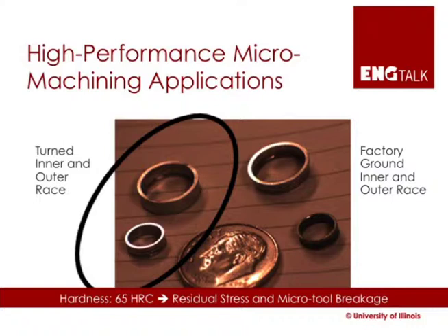And when you're machining such hard materials using microscale tooling, there are two things that you have to really take into consideration. One is, of course, the breaking of our tools. Again, these tools could be finer than the diameter of your hair. And the second thing is when you're cutting such hard materials, there's extreme heat and high cutting forces that are produced, so you might end up adding residual stress in the part, which again needs to be carefully monitored. So the way to get around these problems is obviously with the use of cutting fluids, which is what we use at the macro scale also.